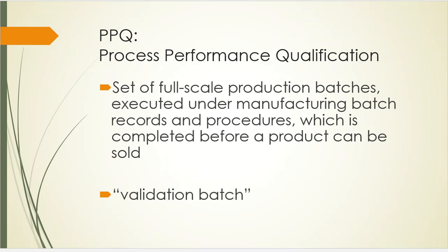There's also something that we call process performance qualification, and this is called PPQ. PPQ is a set of what they call full-scale production batches. So now that everything is in place, now that all of my equipment is on the production side of the house, it is operating, it's performing, we've done checkoffs on all of those. This is like a full-blown batch that gets made, and this is just testing everything to make sure that things are going to go according to plan. That is what a process performance qualification, or PPQ, is all about. It is full scale, it is all production from step 1 all the way to the very end.